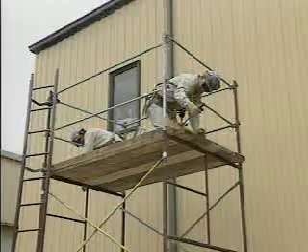The proper care and use of a tubular welded frame scaffold is very similar to other types of fixed scaffolds. For example, the scaffold should be inspected before each use to ensure that it remains in good condition. Also, workers who use the scaffold must follow the same basic safety guidelines that apply to other types of scaffolds.